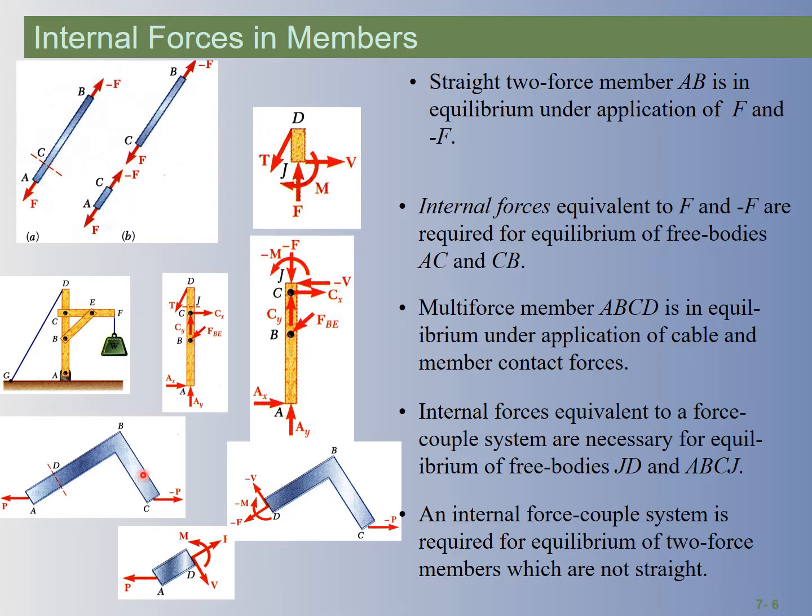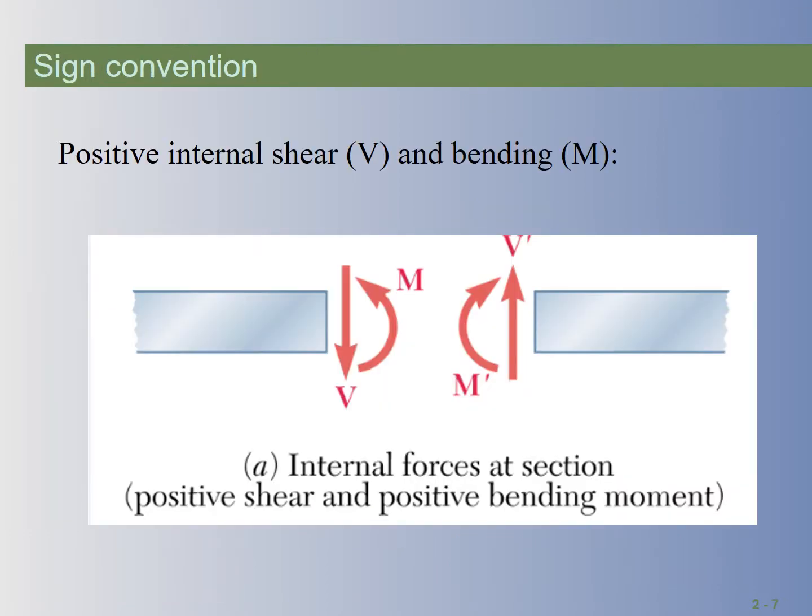So just think about right before this fails, is it going to bend before it fails? If it's bending before it fails, there's a bending moment in there that's going to have to be fighting against that material deformation. If it's pulling apart like taffy, that's going to be just a straight axial force. Or if there's some kind of a shearing force happening. So just think about how it breaks, and that will tell you how to write the reactions. The safe way is to always just include axial, shear, and bending force inside of there and slowly go through and see which ones are going to be present inside.